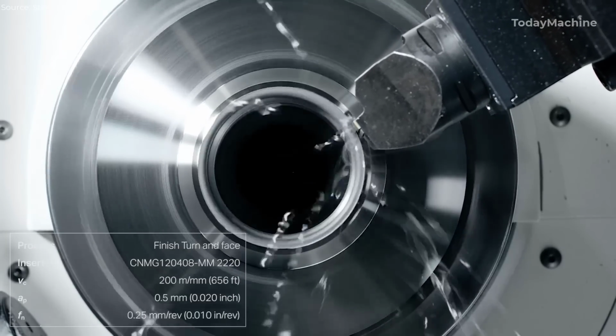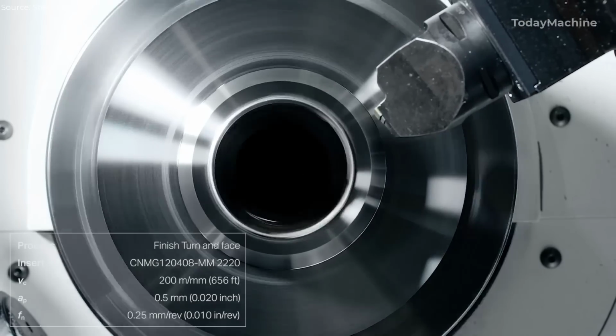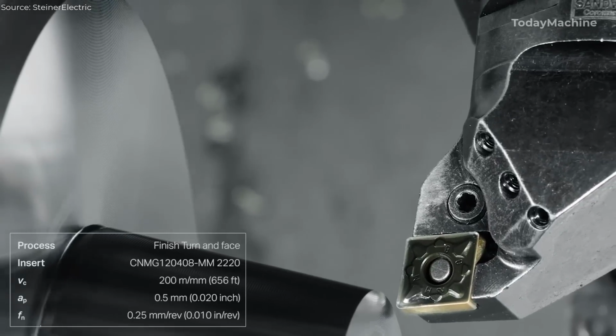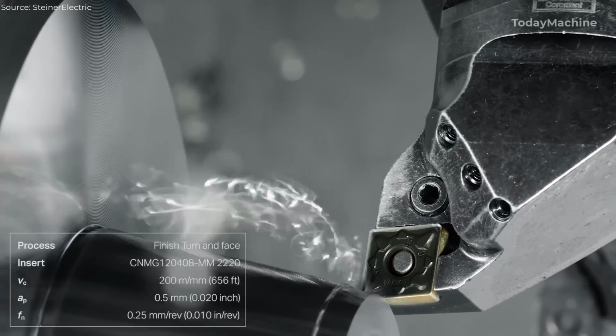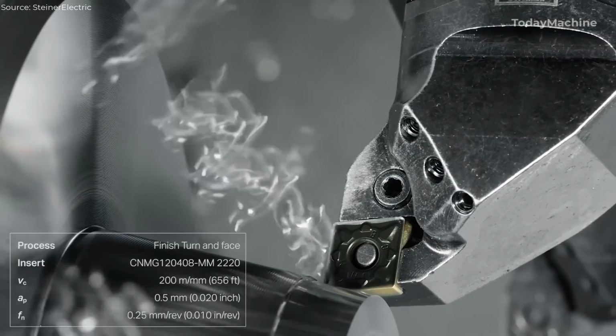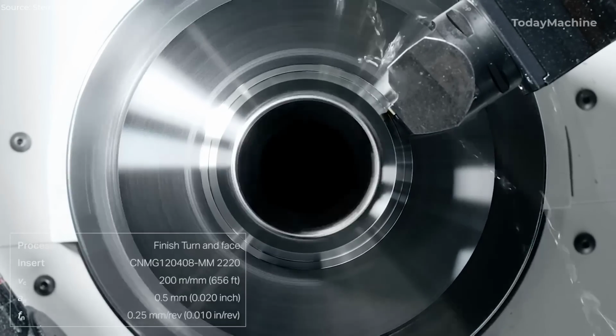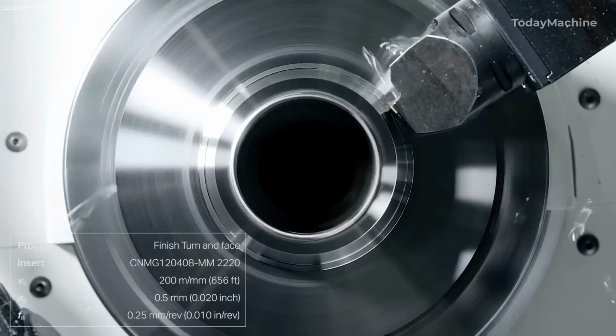The inserts perform exceptionally well in conditions ranging from continuous cutting to light interruptions, and they are optimized for use at average to high cutting speeds. Their design, combined with the high-performance substrate and precise post-treatment processes, makes them an excellent choice for ISO-M machining applications.